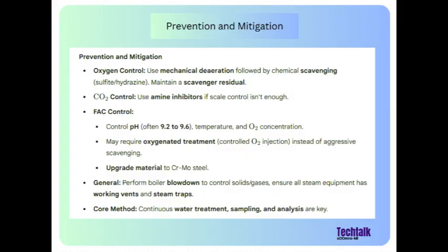Yeah. Which brings us neatly to mitigation. How do we fight back against all this? Let's start with standard prevention. Oxygen removal. Step 1 is mechanical deaeration. Basically, you boil the gases out of the water under pressure and vacuum. But you said that's never perfect? Right, so you follow up with chemical scavengers, typically catalyzed sodium sulfite, or for higher pressure systems, hydrazine.